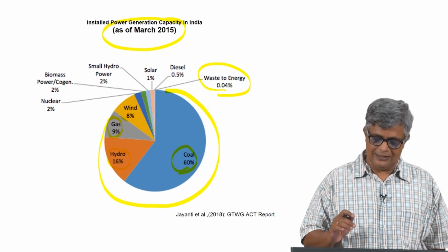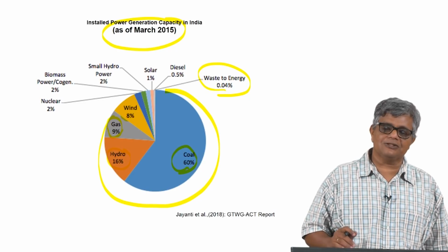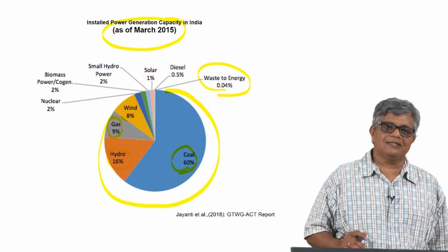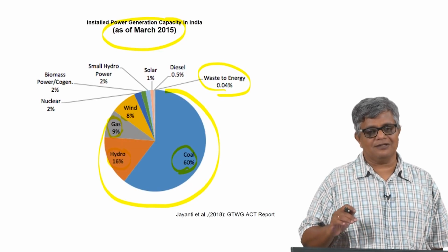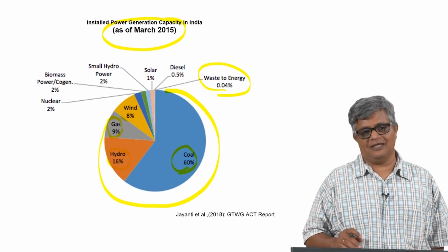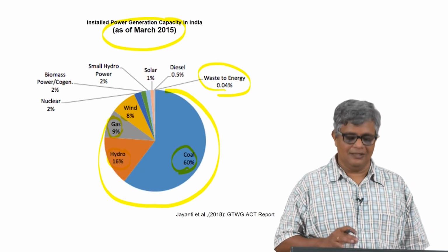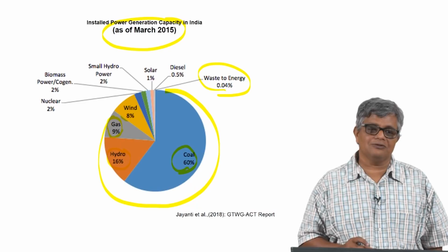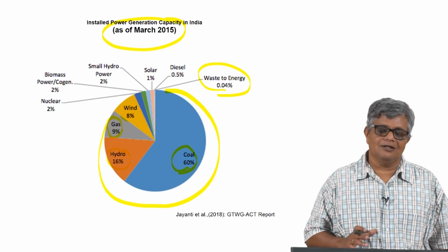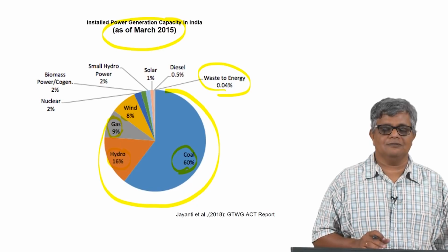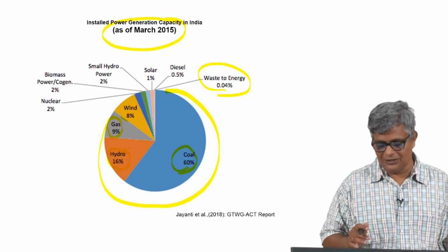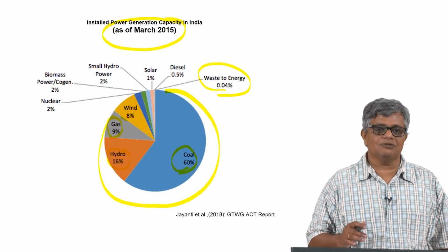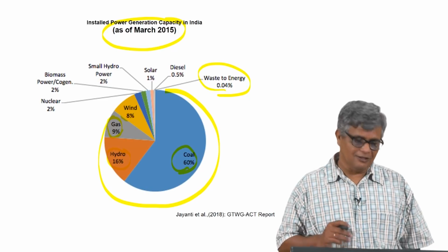So, the installed capacity is different from the number of maybe billions of units of electricity that are produced. So, power energy generation is different from installed power capacity. There is a vast difference between these sources. Fossil fuels are good from that point of view, that you can hope to get 80% of the rated power from the fossil fuels, whereas conventionally new renewables like solar and wind will hardly give you 25 to 30% of the rated power in terms of energy realization.